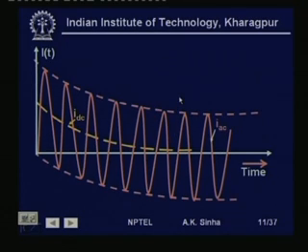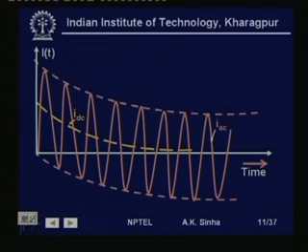So, this is the kind of current that we would see in case of a short circuit on an RL circuit. Now, systems in power systems are very similar to this. If we take a synchronous machine, it has a winding which has a leakage reactance, and it also has some reactance to take care of the armature reaction, and it has a winding resistance. All these put together, we call the synchronous impedance. So, it has resistance and reactance or inductance in series.